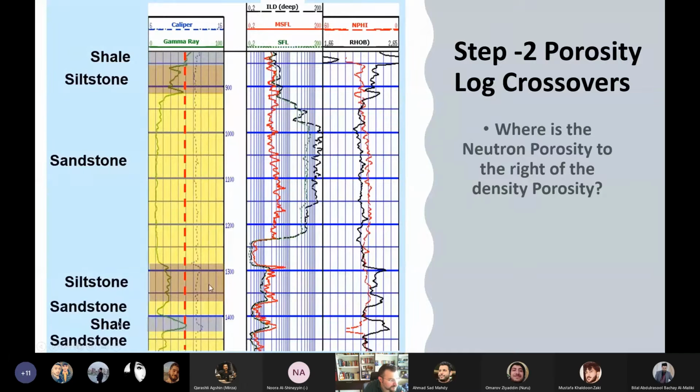So again, it can be understood here, this shale formation again. When you compare it with your density log, I understand that this is shale. In the gamma ray, it gives a lower value, but I always have to match it with other logs. This is very crucial. So when I match this one with the density log, I can understand that it's directly shale. I am in the shale level, right? So your gamma ray gives a little bit lower value, but when I match it with the density, it's directly shale. All right.